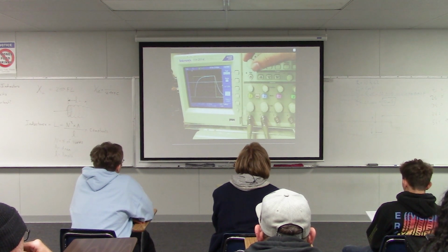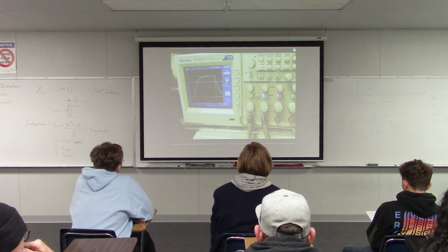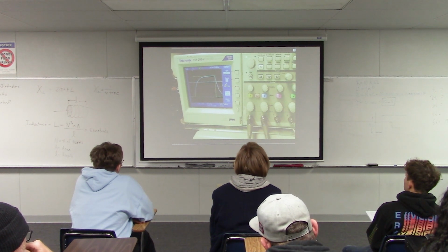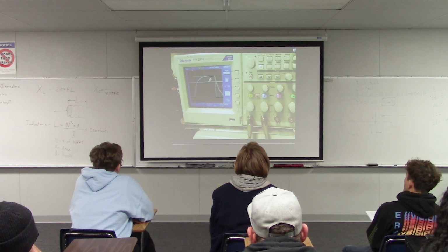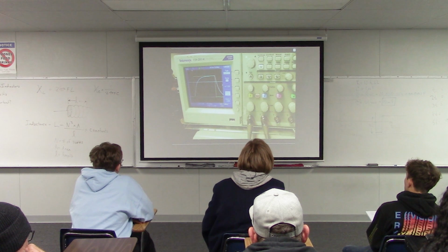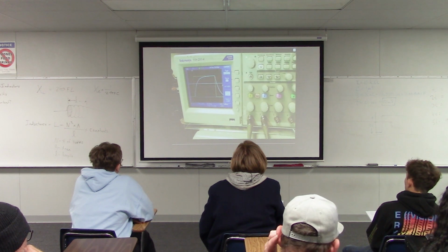What you'll notice here is that there's this measurement that's labeled with this triangle and then V. This triangle is the Greek letter delta, and it stands for difference. So this is the difference in voltage between the two lines. We want to show a 6.32 volt difference between those lines, because that's going to be the amount that it takes to charge up this capacitor, or for one charge time.